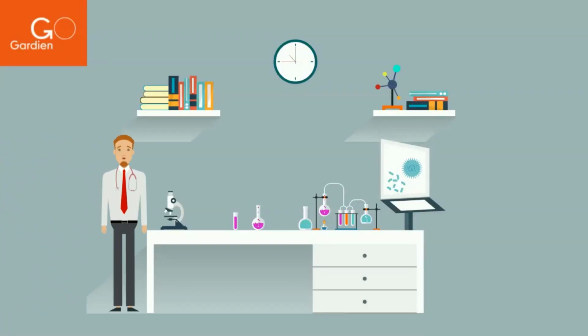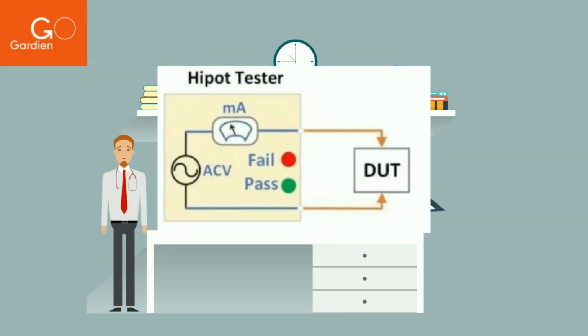Thanks again. A Hipot, short for high potential test, determines the ability of electrical insulation to withstand normally occurring overvoltage transients. The Hipot tester applies high voltage to the insulation barrier of the DUT and verifies there is no breakdown. It is a simple pass or fail test performed as a type test on a representative sample unit or as a routine production test. Maximum allowed leakage is usually in the range of 0.1 to 5 milliamperes, or as specified in the test standard. The actual leakage value for each DUT may be recorded for quality assurance.